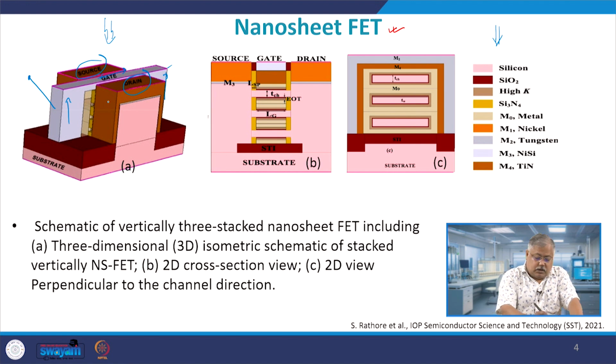Now, this source and drain, obviously there will be a metal contact which will carry it to the next stage, or from where you can give a bias to these devices to operate it in the saturation linear or nonlinear region. However, the gate, if you look very carefully, is surrounded in all sides, but the top gate is having a bit thin structure as compared to the two side gates. So, you have the gate surrounding in all the three directions, right, in this manner.